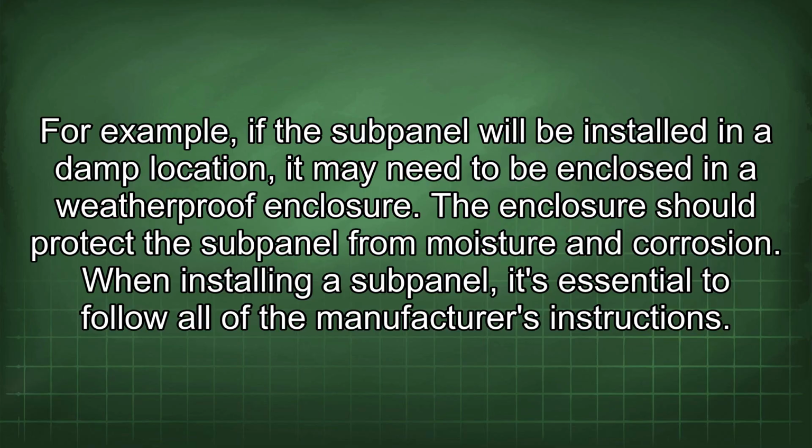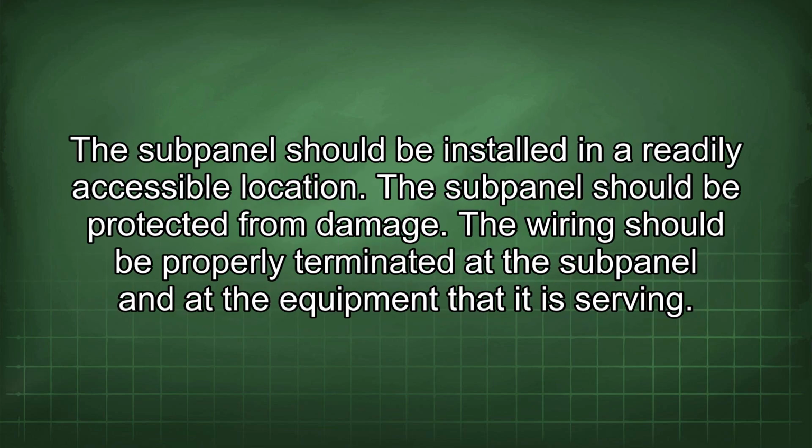When installing a subpanel, it's essential to follow all of the manufacturer's instructions. The subpanel should be installed in a readily accessible location. The subpanel should be protected from damage. The wiring should be properly terminated at the subpanel and at the equipment that it is serving.